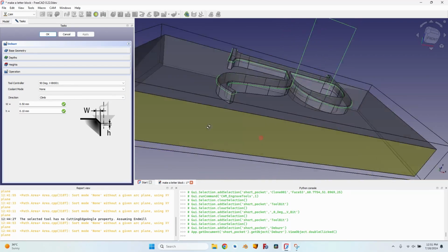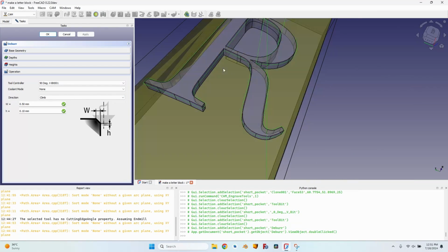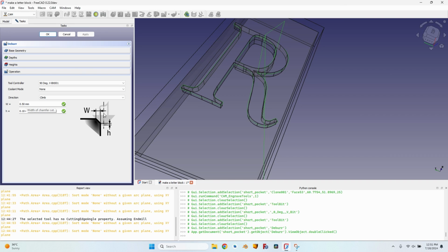Now everything works okay. As you have noticed, I haven't used the chamfer tool in the part design workbench because that generally messes up things. So when making models for the CNC, it's better to forget about chamfering, just add them later based on a straight line on the correct height. This will calculate correctly everything. If I had a line lower, I would have to change the height and everything would be messed up.